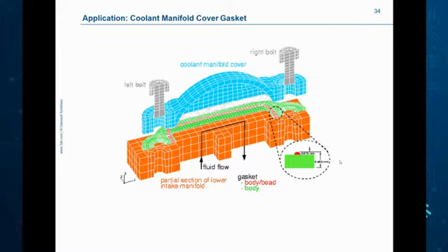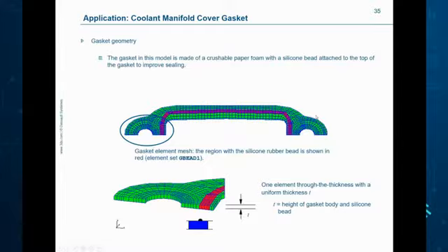So the gasket in this case is modeled with gasket elements. In fact, that's the picture that I showed earlier with the body region and the other red gasket region, and those had two different behaviors. This is a model with symmetry, so it looks chopped in half here. And we're going to have a series of load steps.